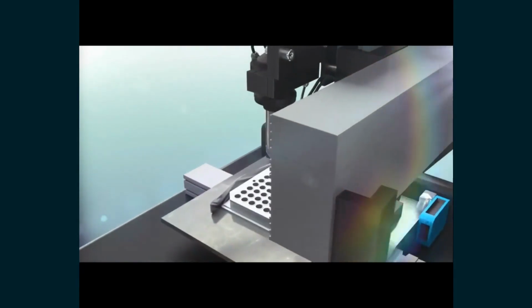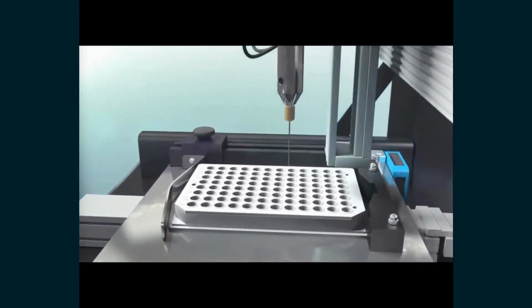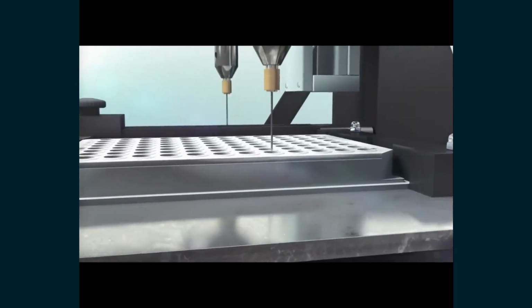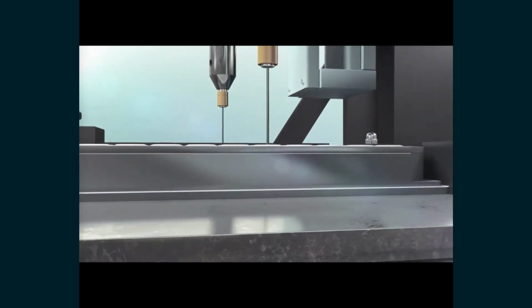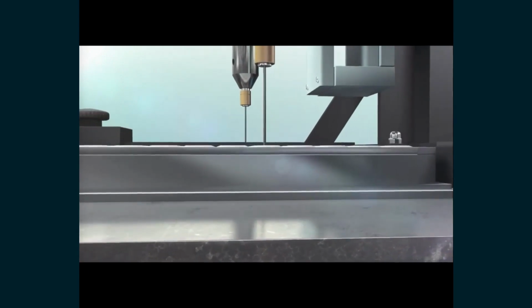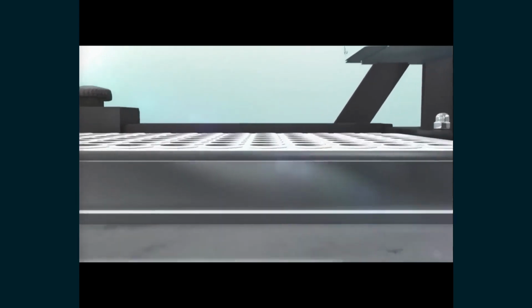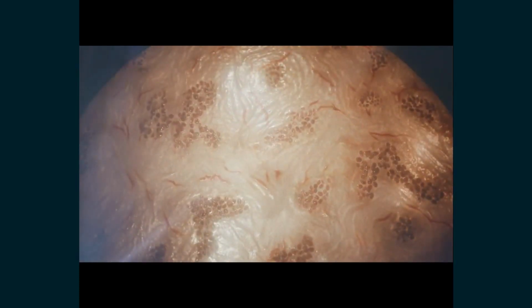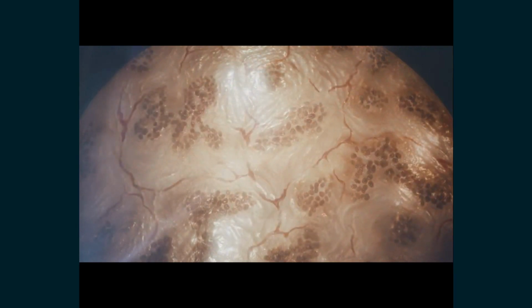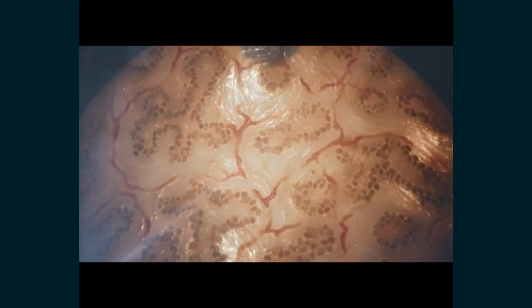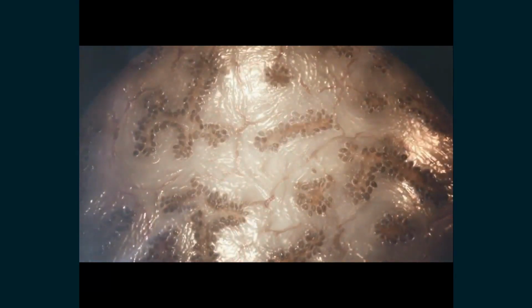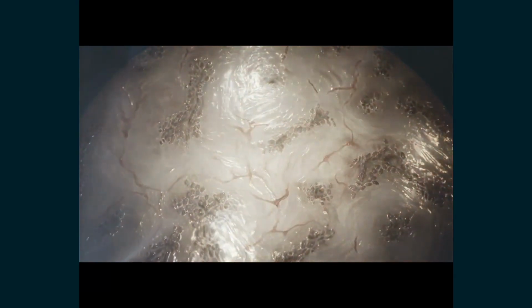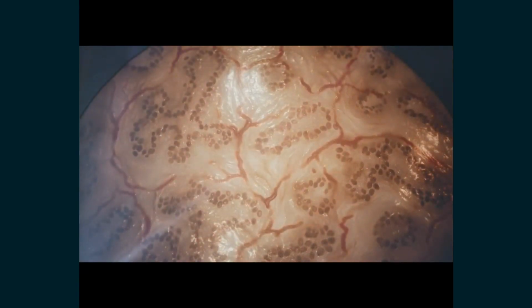3D bioprinting works similarly to FDM 3D printing and is in the material extrusion family. It uses materials discharged from a needle to create layers. These materials, known as bioinks, are mainly composed of living matter such as cells within a carrier. Carrier materials include collagen, gelatin, alginate, or nanocellulose. These carrier materials act as a molecular scaffold for the structure to grow and to provide nutrients to the living matter.